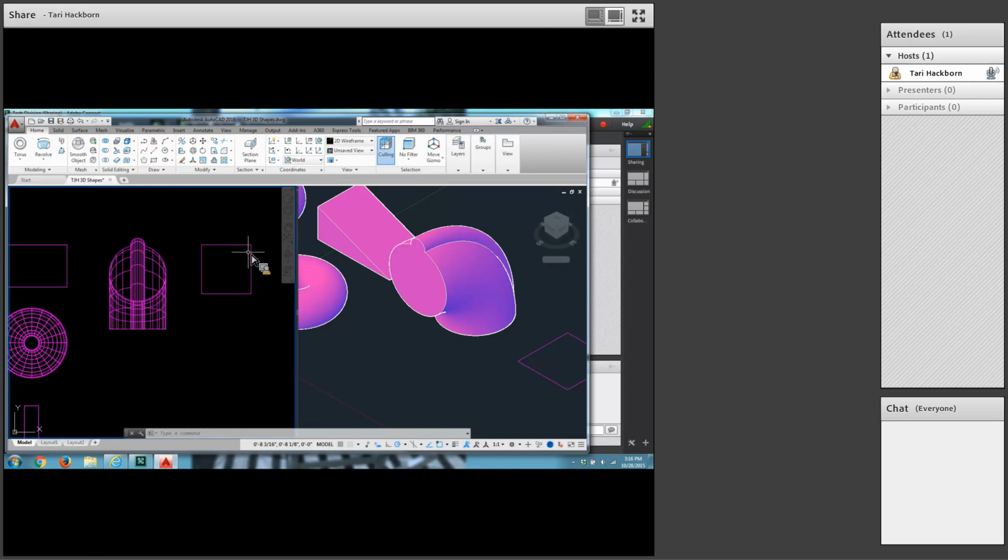The line that's going to be the line to revolve around. Okay, line 7 3/8, comma 6 3/4. Okay, that's the beginning of the line. And drag it straight to the right for 3/4 of an inch. All right.